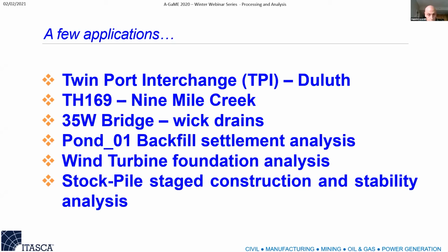This is a typical case in which for a very soft soil, there were probably 50 borings and 0 CPTs, and everybody was talking and fighting over the oedometer modulus at layer number 9. And I said, why don't we do some CPTUs and try to understand it better? And that's what happened. Wind turbine, again, is a foundation analysis and design in which ground improvement was debated, but through the use of CPTs, we were able to determine that ground improvement was not necessary for the performance. And then stockpile stage construction for stability analysis, again using CPTs, in particular the time-dependent dissipation test to determine the consolidation property of the soil.